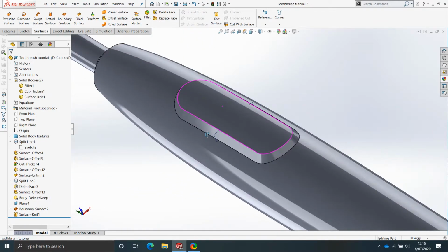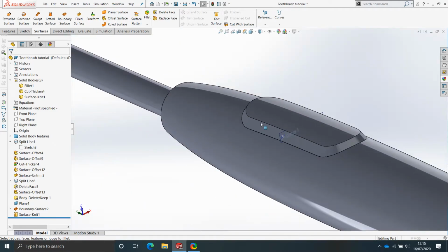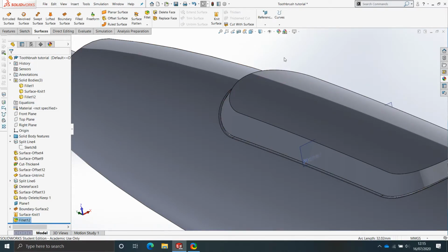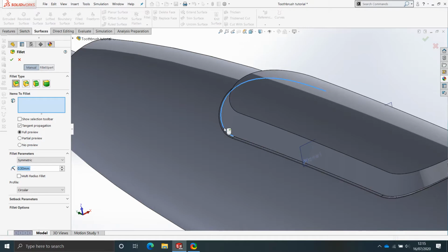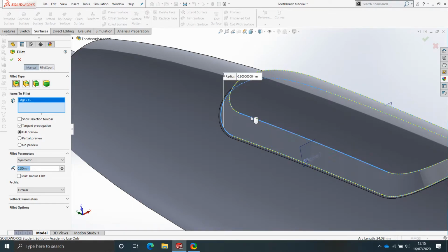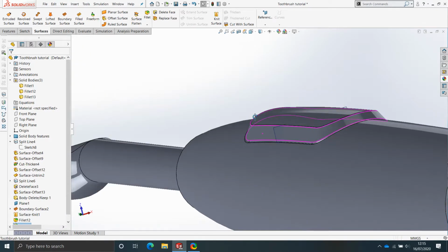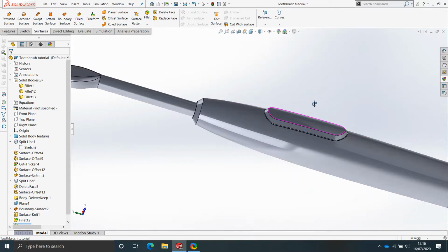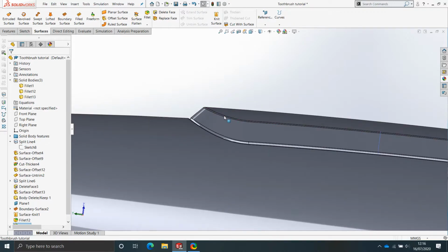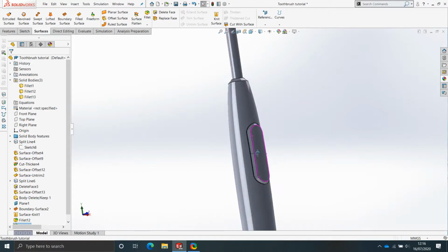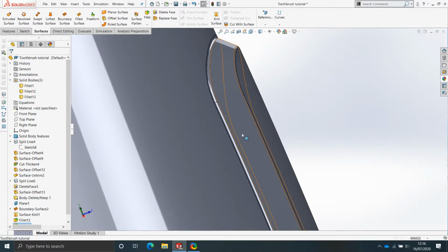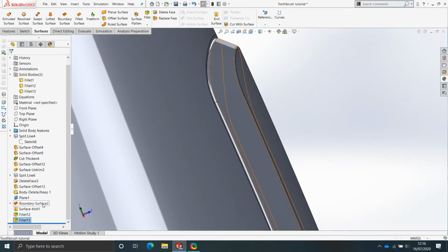And that's pretty cool. And again, I'd say add a little bit of part line definition using the fillet tool. So add in, of course, and we can't fillet multiple bodies, so that's something you'll get used to as well. We have to do multiple fillet features for multiple bodies, and that's pretty cool. So we now have that raised surface, and that's a little bit of an extreme raise, but we can go ahead and modify that if we wanted to.